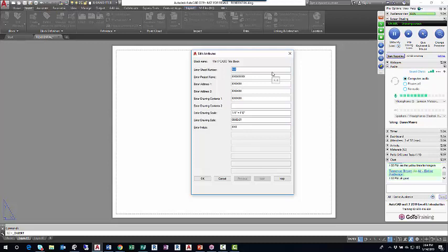I'll fill these out, you don't have to. Sheet number could be something like, for fire protection, FP, I'll capitalize FP, or for civil could be C, or for architecture could be A, and then I'll go 201, like A201. I'll hit enter. So just enter class or enter project name. I'll call this class file. Enter. Enter address. I'll type in 6361 Walker Lane.